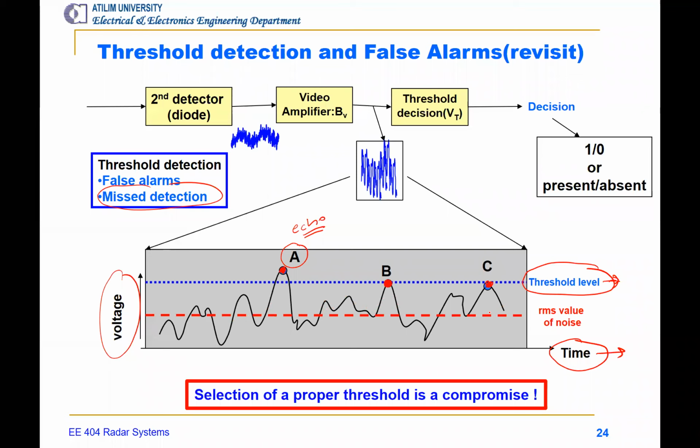So we have to think about how to determine this threshold when we have surface or sea clutter, where there's a dynamic environment. The clutter is varying with the time and position of the radar, or motion, or the land or sea itself. So we have to make this dynamic or adaptive.